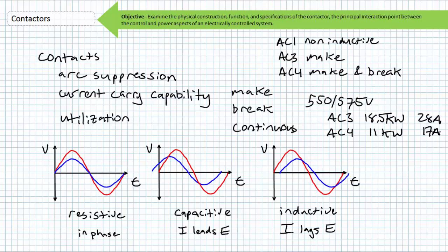Again, consider an inductive load containing a magnetic field. If the current is suddenly terminated, the collapsing magnetic field could generate a large voltage spike to keep current traveling in the same direction. A solid-state contactor with zero crossing detection will purposely extend the closure of the device past the receipt of an open command until the next zero current crossing to prevent this event from happening. We'll return to discuss solid-state contactors, soft starters, SCRs, and thyristors in later lectures.